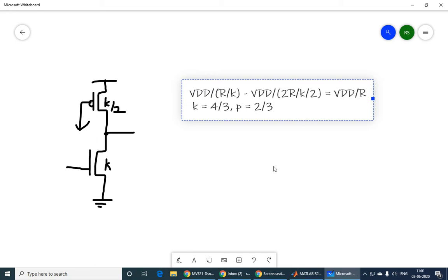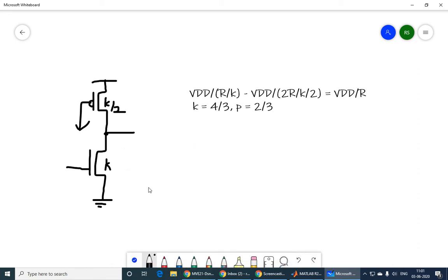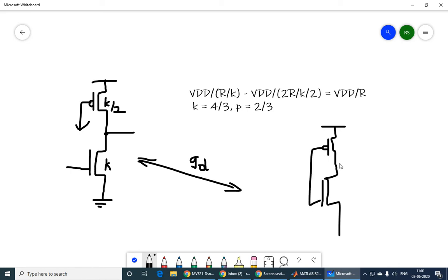Now the next thing is we can calculate the logical effort also. So similar to before, we have GU and GD. So we will calculate GU, we'll calculate GD. Just like before, you size the network with an unskewed static CMOS inverter, and the size should be according to the pull down network. So that is what we have to do.